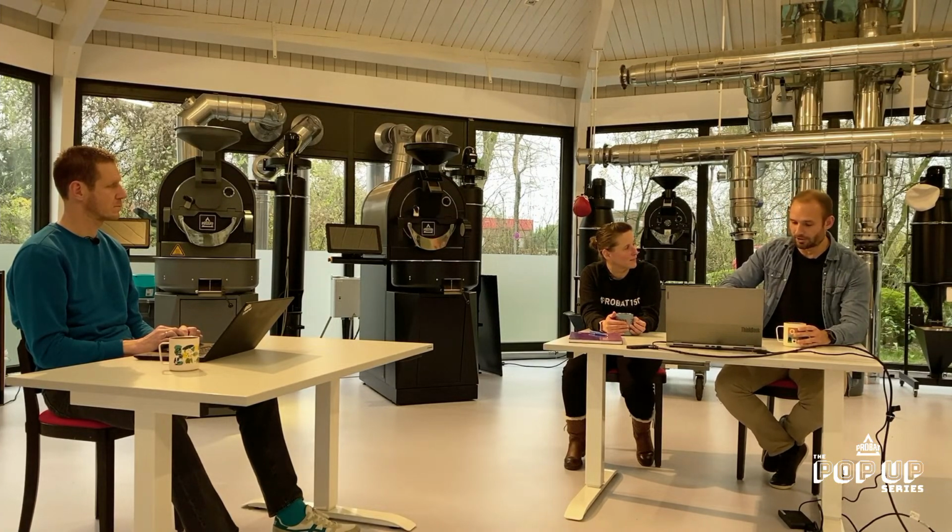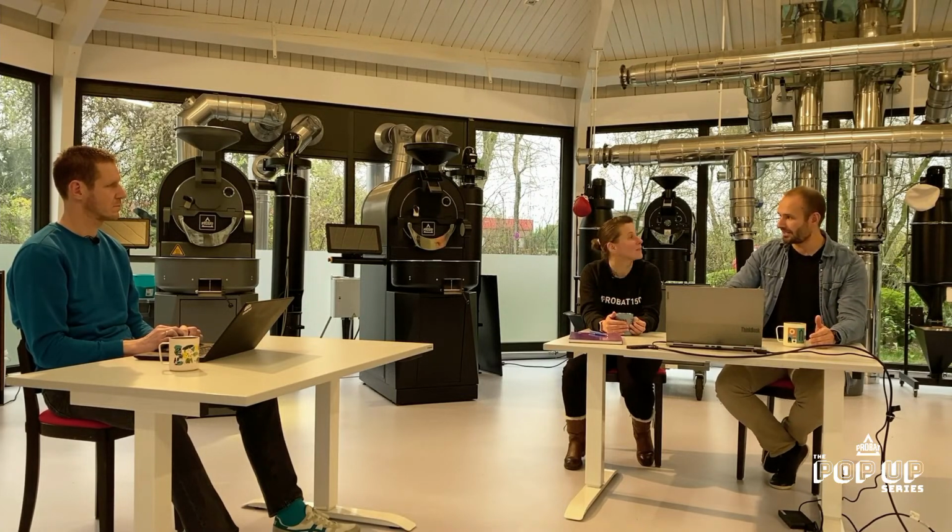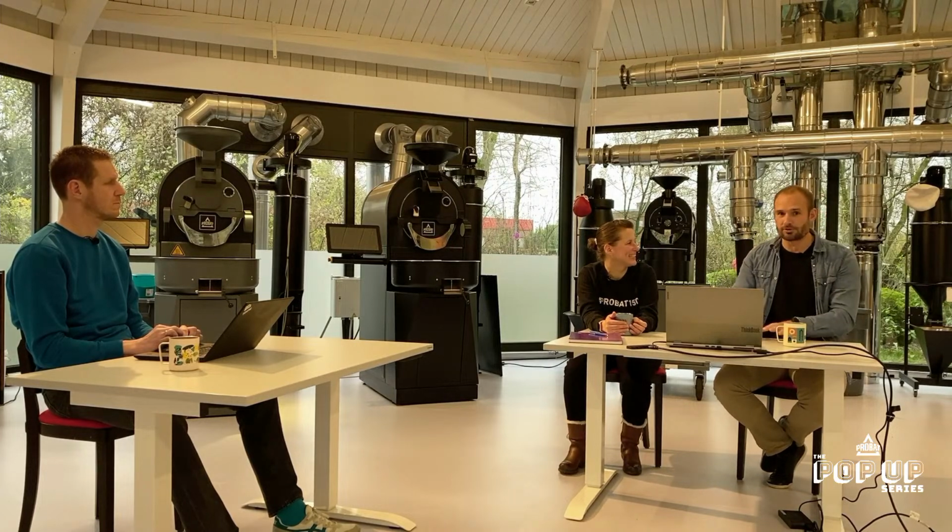Because let's say you were over your rate of rise, you were too fast. And then the controller is going to be like, oh, I was too high, and it's going to try to come back to your initial rate of rise. And let's say it does that and does everything perfectly. If you then look at your product temperature, it's going to be offset to the top. It's never going to return to the real product temperature curve, even though the controller did everything right.